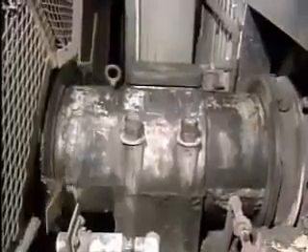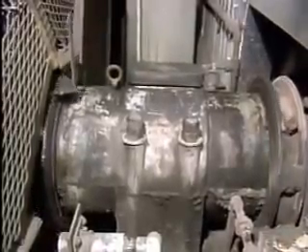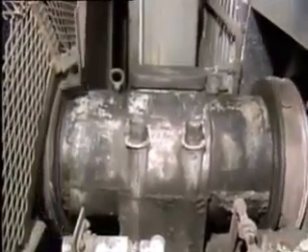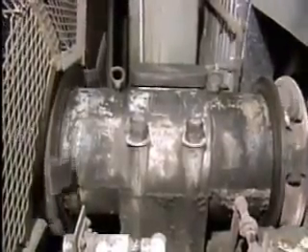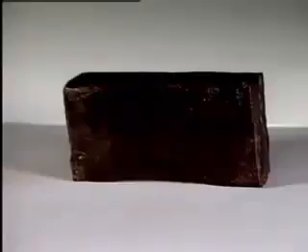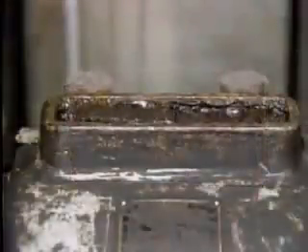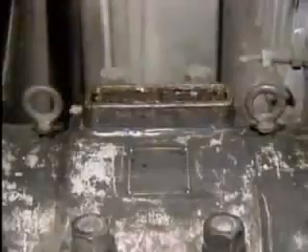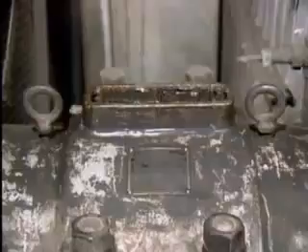This shaft, for example, turns a device that rotates through the hot gases produced in a boiler. The hot shaft turns in a sleeve bearing in this housing. The shaft and the bearing must be lubricated with a grease that will stay in place under high temperatures, like this hard grade 6 grease. A block of the hard grease is placed directly on the shaft through a hole in the housing and the bearing.